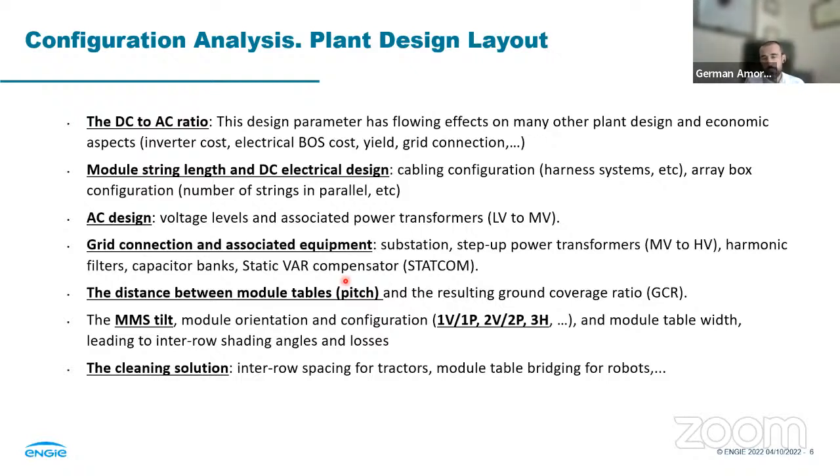Important point about the pitch, that we have a constraint. Obviously, the supplier of the tracker will say, okay, you have a maximum 15 or 14 distance between rows of tracker, because otherwise all trackers could be considered edge or external trackers, which could have a big impact in the CAPEX also. So we have a discount treating pitch, always the maximum pitch that we have, obviously intended to improve the performance of the production.